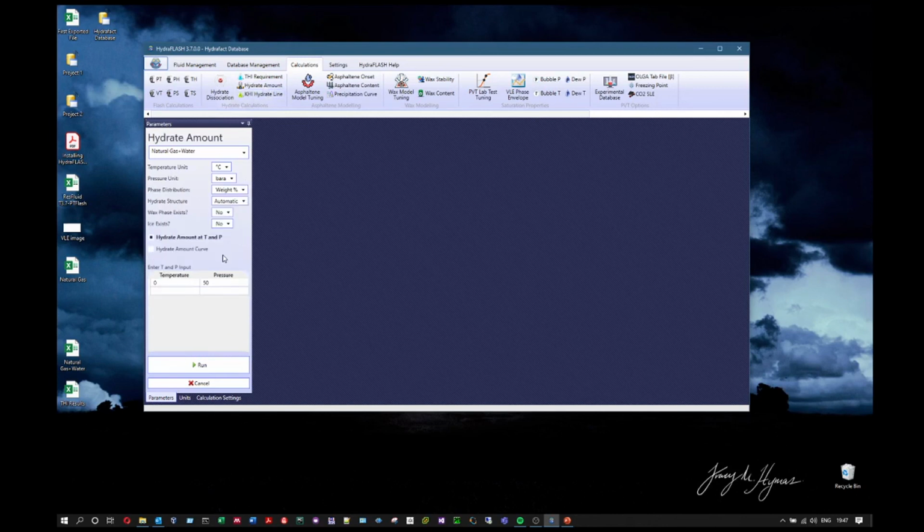The hydrate amounts will predict the amounts of hydrate that will form in an infinite time in equilibrium conditions, which is an ideal condition, and how much hydrate you will have in the system if you are working inside the hydrate stability zone. And the KHI line gives you an estimation of the effectiveness of KHI with the specified CIR in your inhibition strategy.